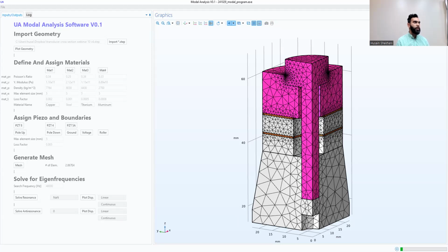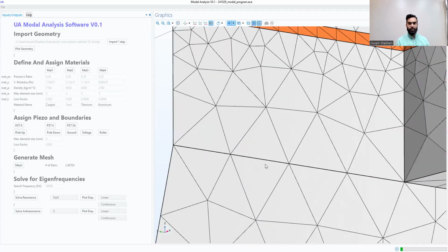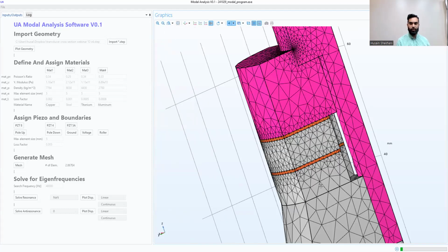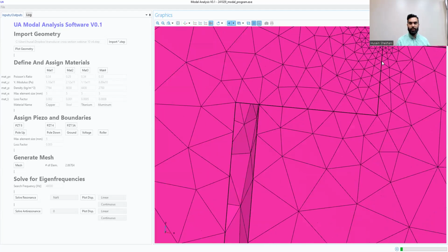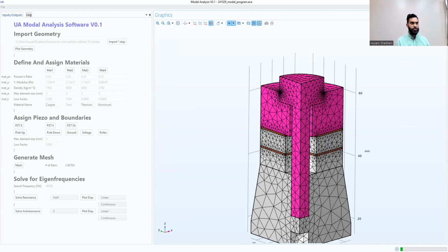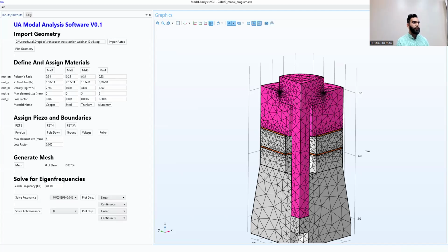Is this mesh all single body or is there contact? No, in this case I didn't put any contact. So they're all conforming, like you see here, all the points are kind of touching. This is problematic. Sometimes there's contact conditions defined, which makes the mesh less accurate, but it ensures that it will solve every time. And right now I do want to make a program that will work every time without too much fuss. So I may include that, and it's rather simple actually to change it if it ends up being a problem for users. The other questions.